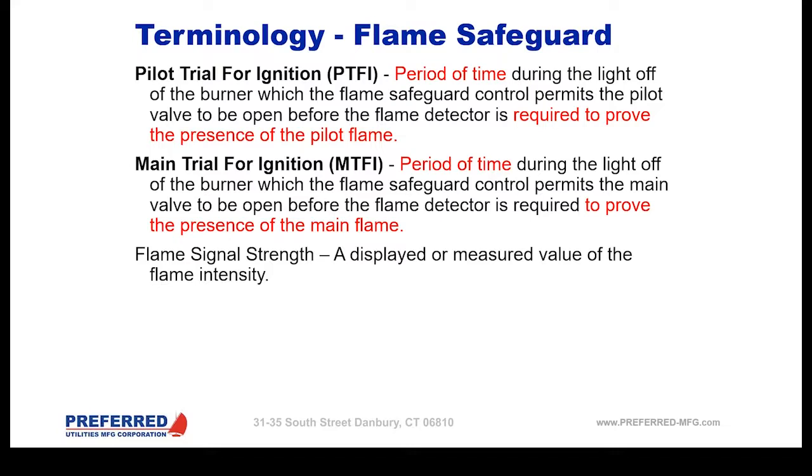strength. This is a very important thing to understand, and it is different on different flame safeguards in the industry. They have different numbers and so forth. So this is something that you would want to go to the particular flame safeguard instruction manual and see what the range is. And that will indicate what a good flame signal is normally.